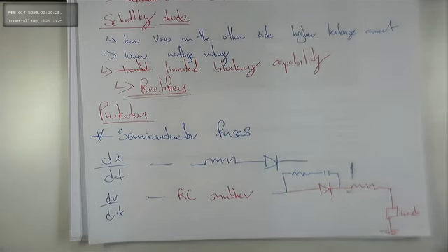You have VFD, the forward voltage, and then you have the reverse blocking region. It is a certain point till where it can block negative voltage, and then it collapses. So we don't want to reach that point. We always have to see the ratings. Whenever you get a device, the first thing you have to do is find the data sheet and look at the ratings.